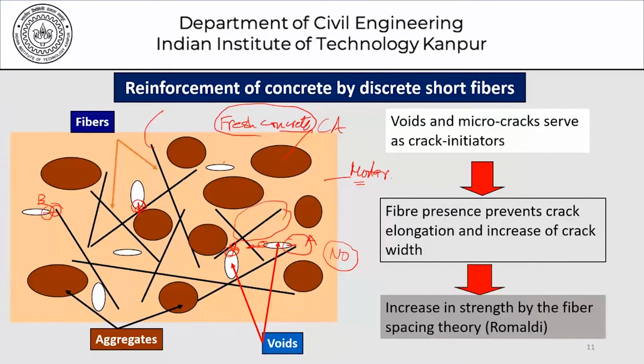And now as far as the discussion of the placeability of fiber concrete is concerned, it's not simply the placeability of mortar or concrete that we are talking about, but that modified because of the presence of fibers. I think it is intuitively clear to you after all the discussion that we've been having for different types of concrete so far, that if I have too much coarse aggregate here, or the amount of mortar here is very less, then can we add a lot of fibers to it?